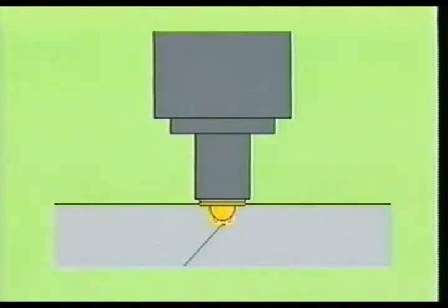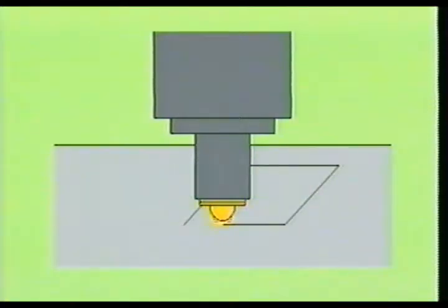High-power lasers are used for welding and cutting applications. These style lasers are typically a CO2 gas device and can generate several thousand watts of power. CO2 gas lasers are extremely dangerous and proper safety precautions must be followed when working on these devices.